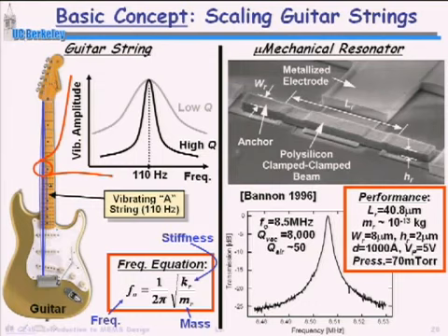So just by applying an AC signal here and tracing the output amplitude versus the AC signal, this now traces out this frequency selective transfer function, exactly what we need for wireless communications. Not quite at the gigahertz frequency that we want, but you could see that making things smaller does increase that frequency. And to get the gigahertz frequency, I'll show you how to do that a little later on. But a couple things are interesting here. At this 8.5 megahertz, the quality factor is 8,000. What does that mean? That tells you how selective this is.